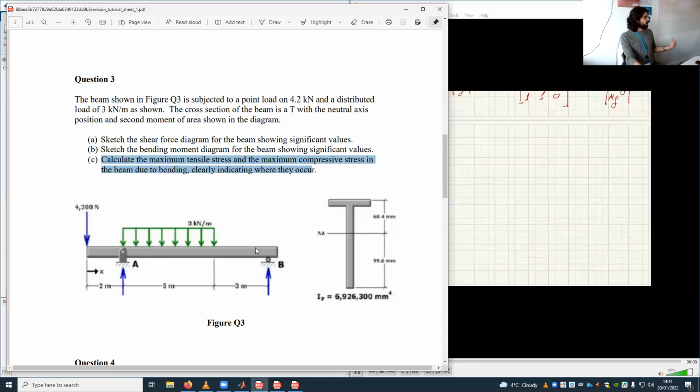So on this section, we can already find out, imagine on this beam, we have to find the bending moment diagram to check where is the largest bending moment. Now on that section that looks like this, which point on this section is the most critical, is the most stressed? What do you think? A point here on the neutral axis? I'd say no, because that's for bending moment.